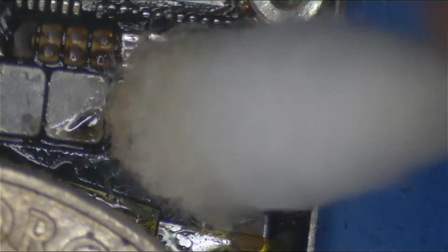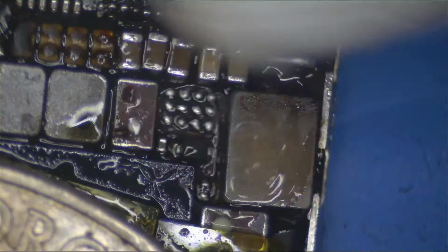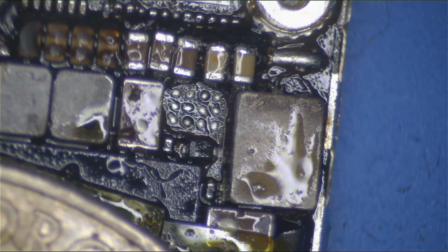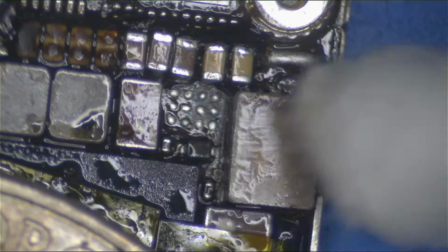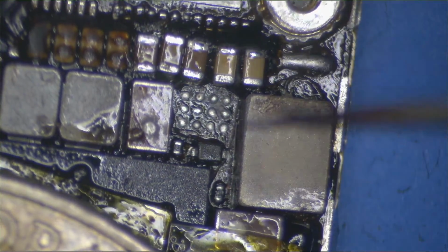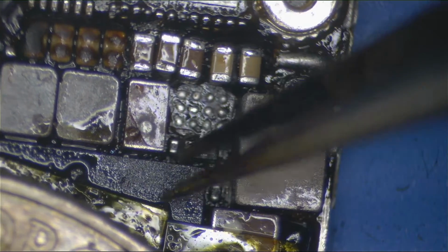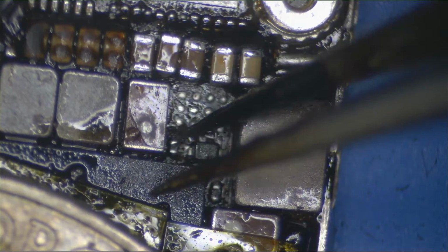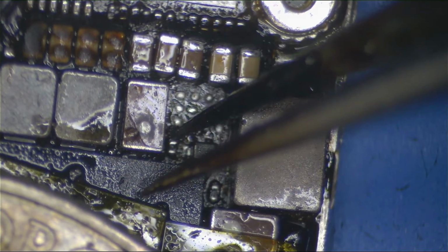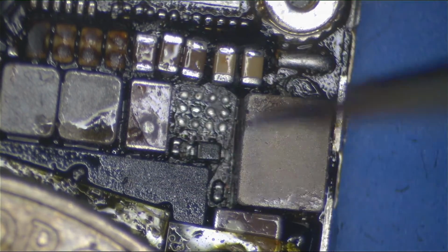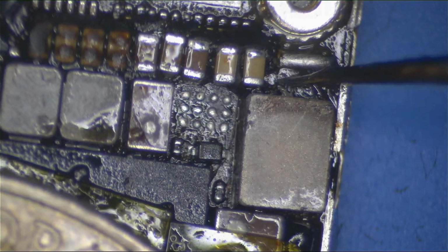So I'm really cleaning it up with alcohol to make sure I can see underneath. And yeah, there's a lot of residue on the sides there. That was a fail. All that on the sides has got to go, or else that's why this chip is not going to sit in place. The same as before, just pick it away. Don't scrape the solder mask.